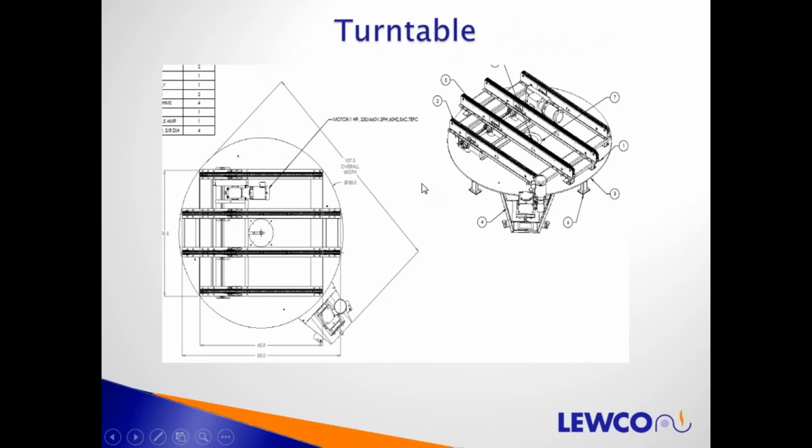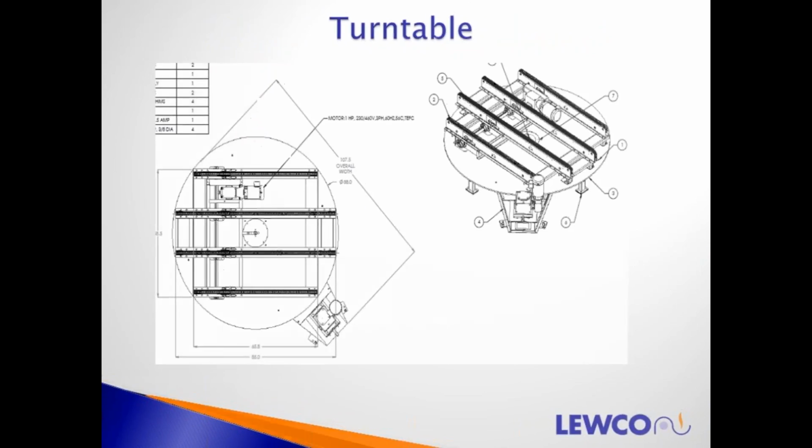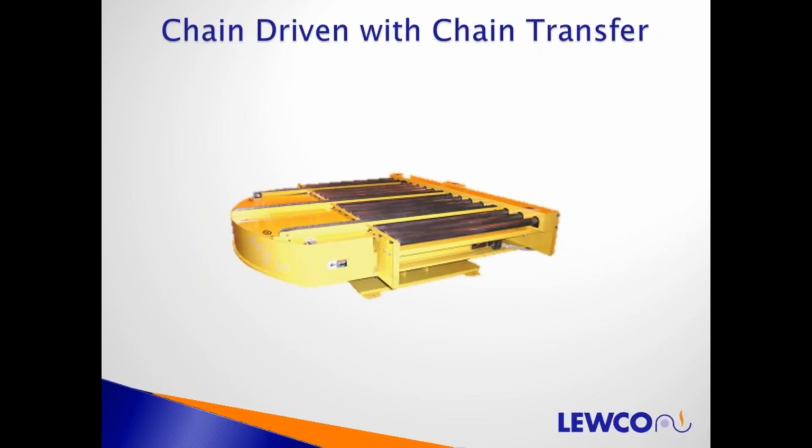This just shows another 4-strand chain conveyor on top of a turntable. Here we have a chain-driven live roller turntable with a chain transfer in it, and this would be used to rotate the pallet orientation in a through line. So if they needed to change orientation, the turntable would rotate and transfer off, switching the orientation of the pallet or product they were using.